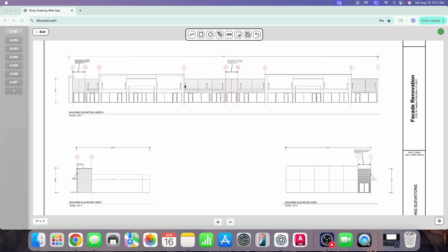So, just for context, over here, as you can see, from C to C.1, this wall goes straight. From C1 to C.2, it goes at a 45-degree angle. And then from C2 to D, it goes straight again. So because this is a two-dimensional drawing, you can't really tell, but this wall is at a 45-degree angle.